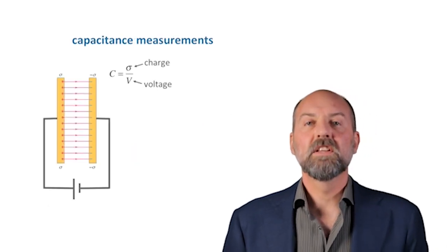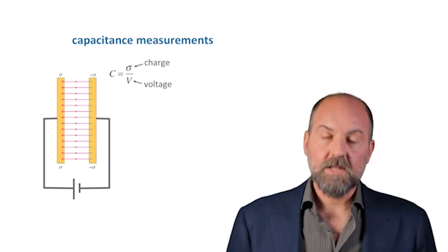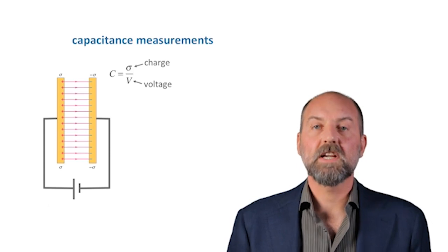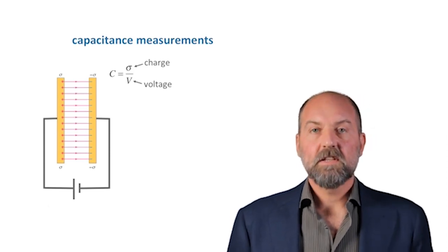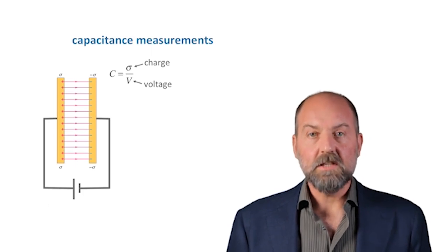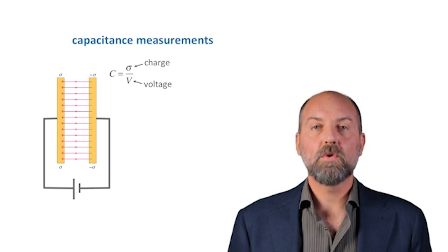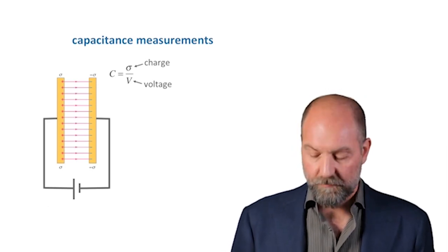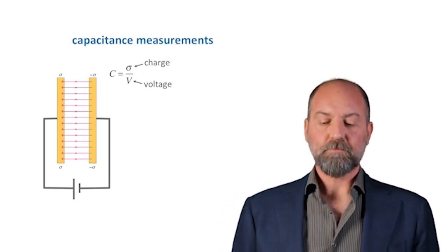Now, let us describe briefly the other main technology that is available for measuring soil water content, which is the capacitance sensor. The capacitance is defined as the ability to store electric charge in any arrangement of electrodes when, of course, a voltage difference is applied in between.